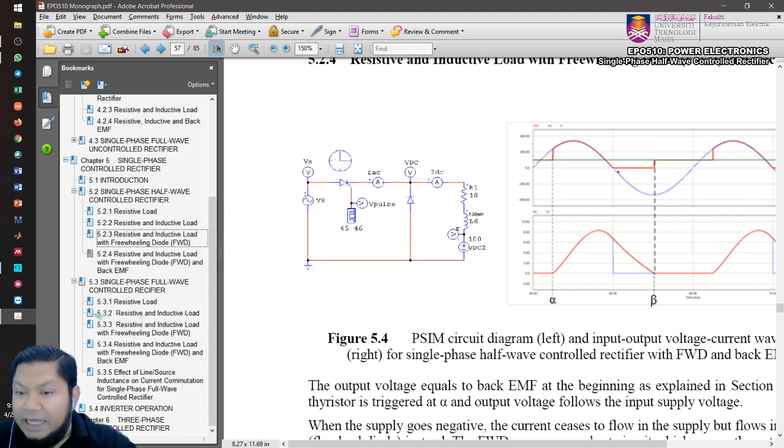until the negative half cycle. Again, when the current starts to flow in that direction through the freewheeling diode, the diode will be turned on and appear as a short circuit. Therefore if you measure at that point, VDC will be 0, isn't it? So that's why you have 0 voltage until the current goes to 0.